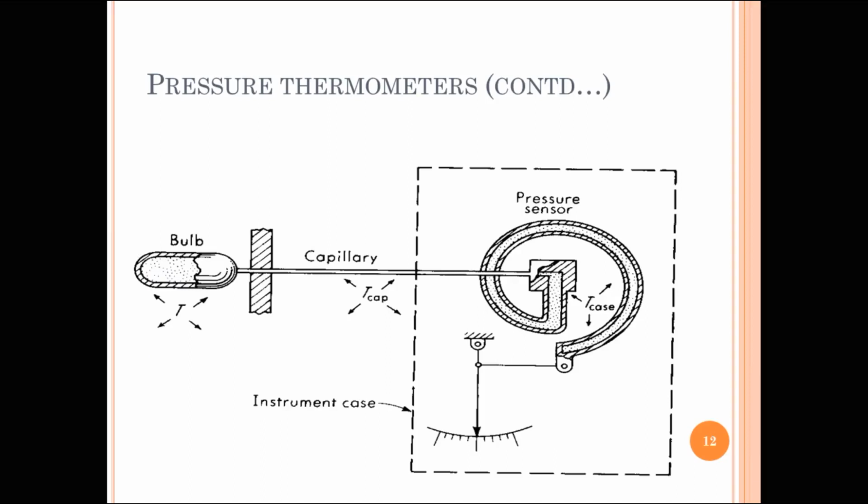Under an initial pressure, the compressibility relative to pressure gauge, that is, the ratio of change in volume with respect to change in pressure, is considerably small. Hence, it has large pressure change at constant volume. The length of capillary tube can be increased for remote measurement.